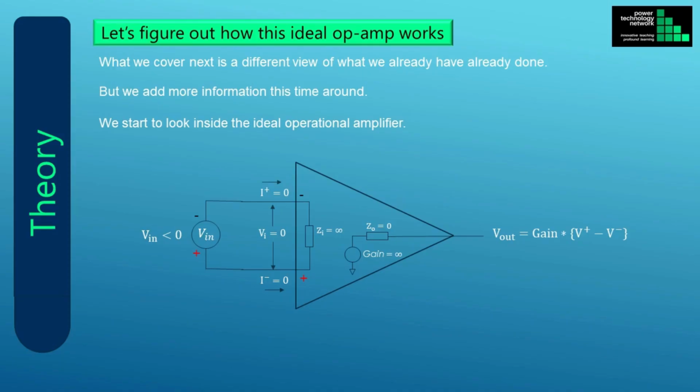The output voltage is given by the now well-known gain equation. The gain equation is simplified, in the usual way, to obtain the expression for the output voltage for this circuit. In this case the output voltage is equal to the negative of the open loop gain multiplied by the differential input voltage. So, it is clear that just like before it is an inverting amplifier.